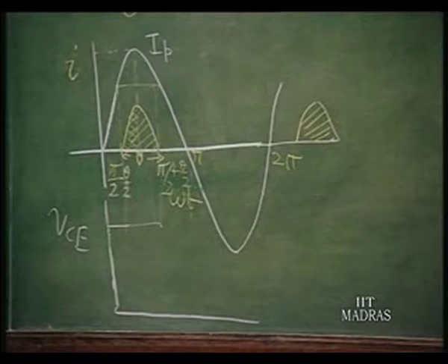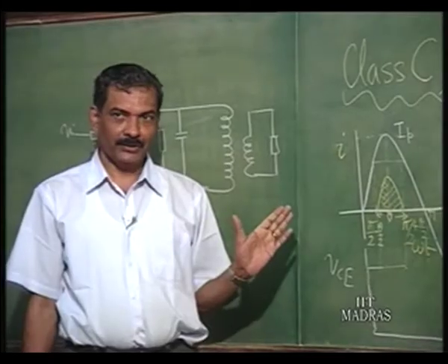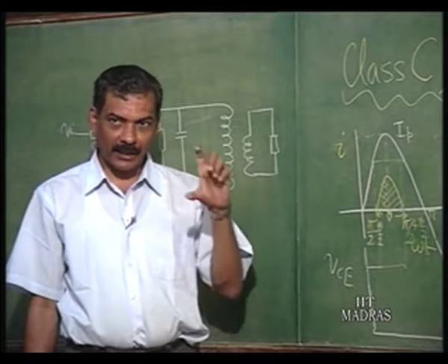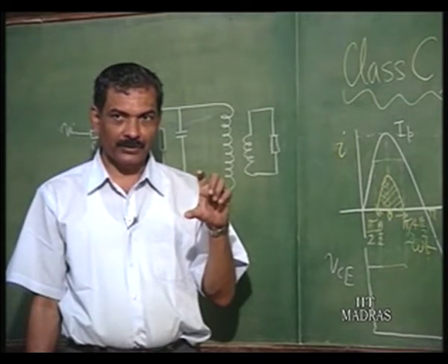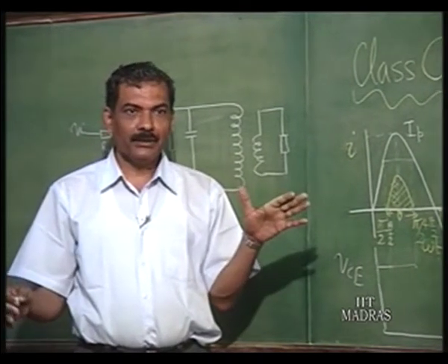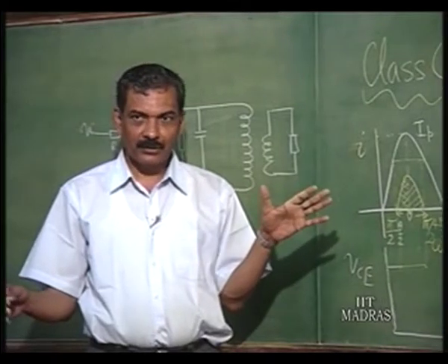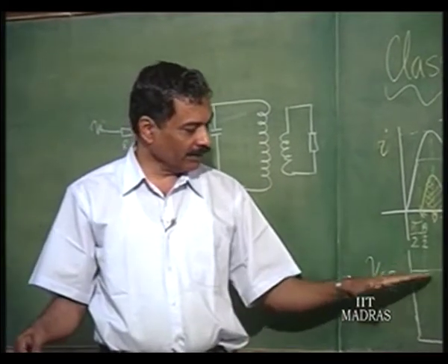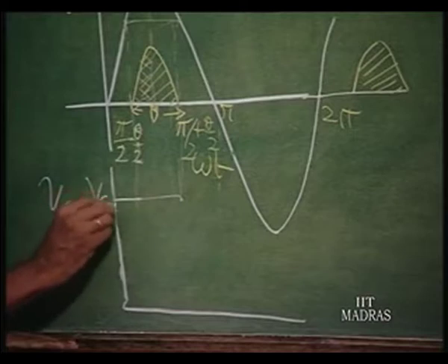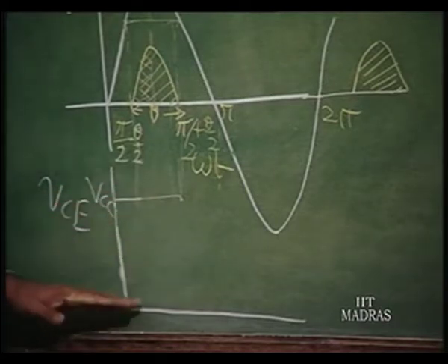Thereafter, this current pulse is going to generate only voltage waveform corresponding to fundamental. So, the voltage that is going to be generated across the tuned circuit is going to be some Vp sin omega t. The Vp can reach as much as, since this is starting with VCC, almost VCC itself, the peak voltage.